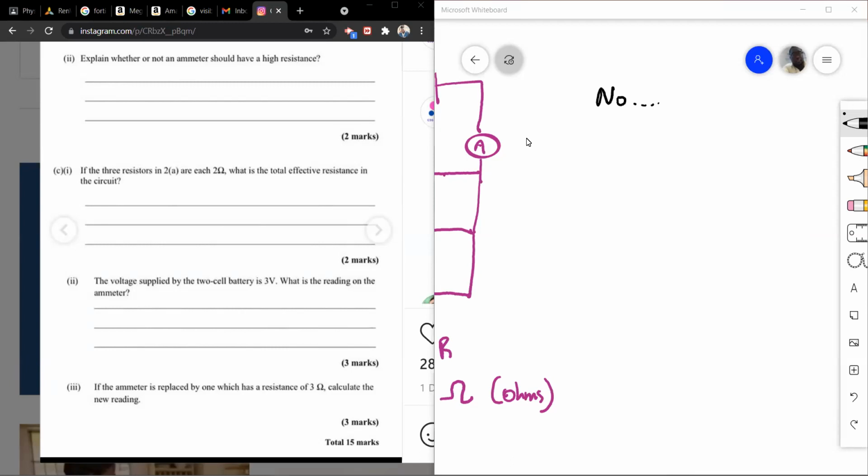That's all I want to know. So you going through and talking about leaving the cell and diverging and converging and doing all of that niceness. Yeah, that's lovely. All right, but you still haven't gotten to the point. The point is, I want my current to flow through, especially if I want the ammeter to be telling me the current in the entire circuit. I don't want a high resistance to minimize the current. You understand? So I want it to be as unrestricted as possible.